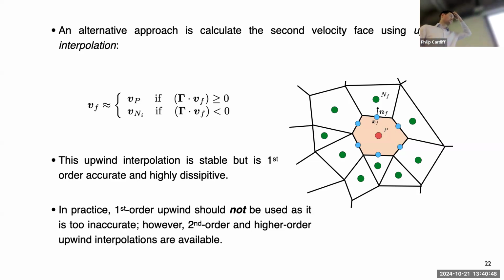So in practice, you should really just not use upwind. People use upwind, but you'd have to use such a fine grid in most cases to get a true mesh independent solution that you really can't be sure you have a fine enough grid. There are second order versions of upwind. Rather than using the value at the upwind node, you use the value there and its gradient to extrapolate to the face. So you get an upwind effect, but with higher order values.